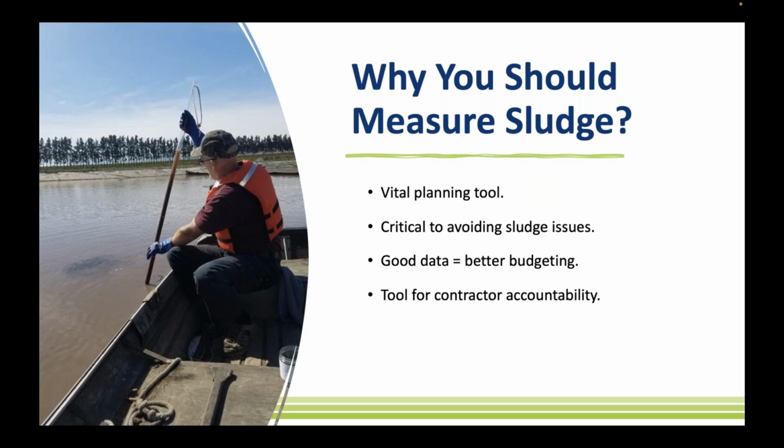The second thing is, if you get that data, now you can budget properly for that sludge removal, right? Now you can understand what's the volume, what are the cubic feet of sludge that I have? And I've seen systems go out to bid without any sludge information for contractors. They say, remove sludge, and the contractor's like, well, how much sludge you got? I don't know. Well, what kind of bid do you think you're gonna get, right? They're gonna have to assume you got a lot, because at the end of the day, they don't know. And you're not gonna do it cost effectively.